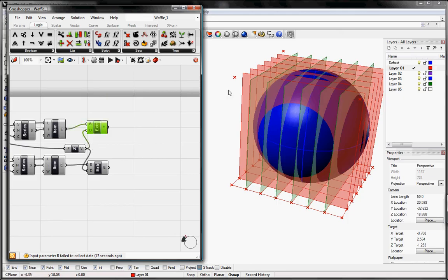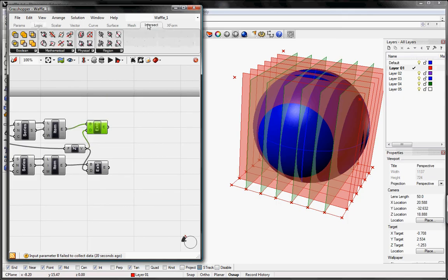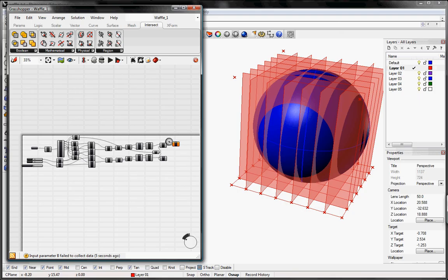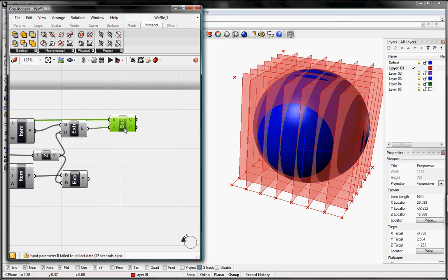Once you have extruded those planes, then we're going to go under intersect mathematical B-rep plane, and that'll equivalently get the individual sections for us. So the P is the section plane, and that's those extrusions we just did. And then the B is the input, the base geometry, which we're going to home run back to our geometry that we set for our waffle. So I'll zoom out and do that really quickly. And then once that one's set, we can copy that down so we don't have to go back to the beginning, and just associate that one with the second extrusion.